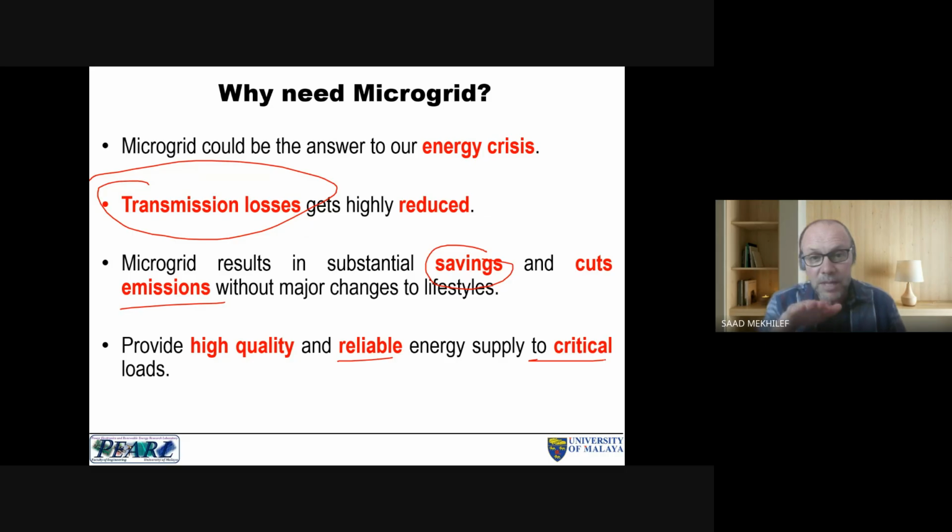If it stops halfway, you have to throw everything out. Imagine that the power cuts off. What happens? The wafer is gone. That's a very expensive wafer. So most of these factories will have redundant sources, such as a diesel generator and then a battery, UPS system. Why do they have both? Any idea?